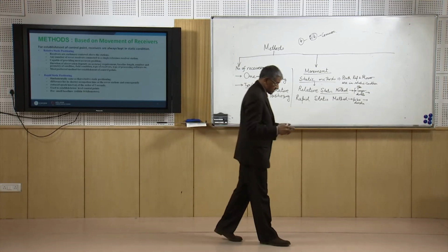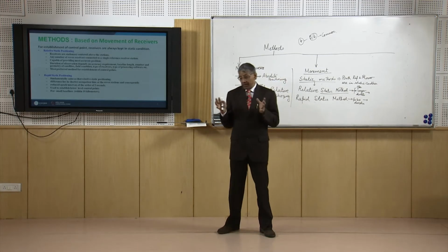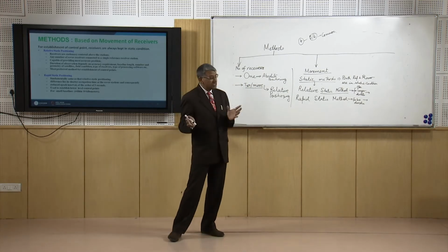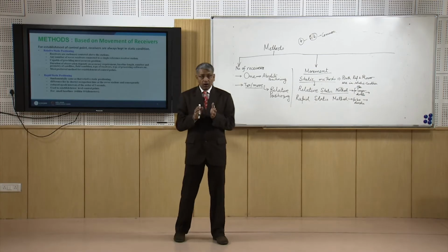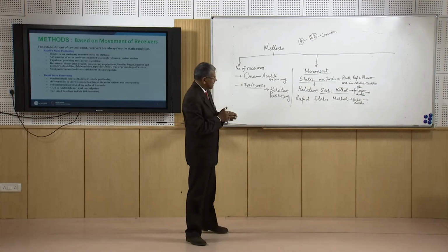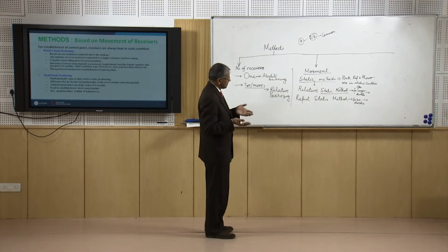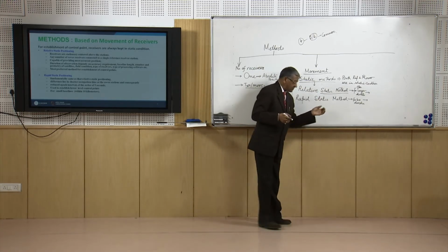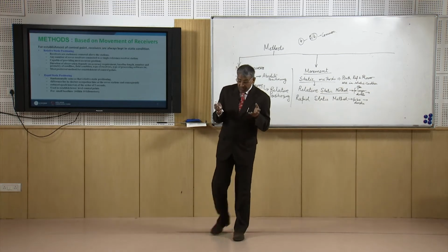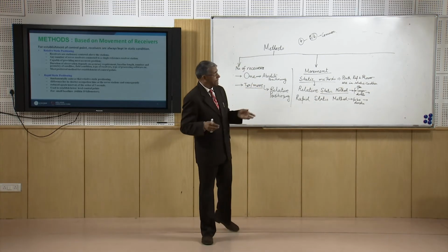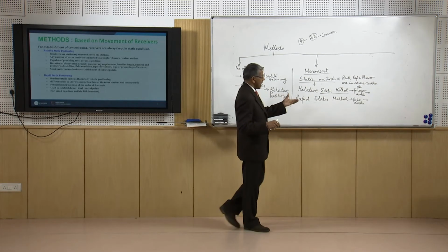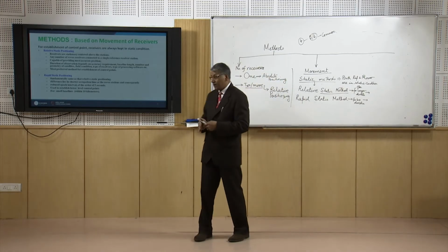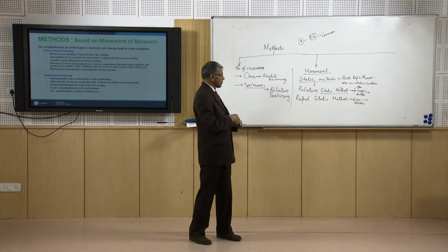In those cases the errors in GPS observation will be more or less identical, so a lower duration of observation will not cause much problem. Rapid static is also useful for control points of lower order, that means accuracy is not that important or not that required.